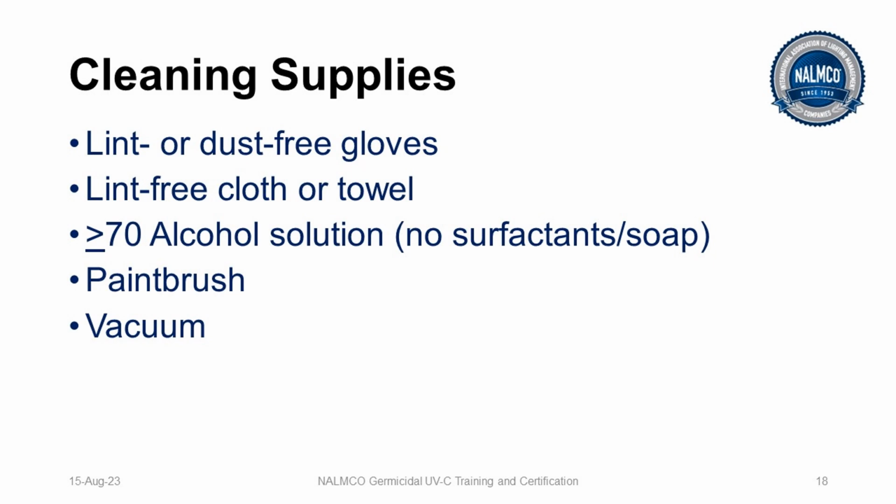Cleaning supplies: ideally lint or dust-free gloves, lint-free cloth or towel, or sometimes cotton balls. You need a solution that's greater than 70% alcohol, and no surfactants or soap. There are some alcohols that also have a surfactant soap in it. We do not want that because that will leave a residual on the surface of the lamp. I often use a paintbrush to clean louvers, and occasionally reverted to vacuuming out the louvers because they were so dirty.